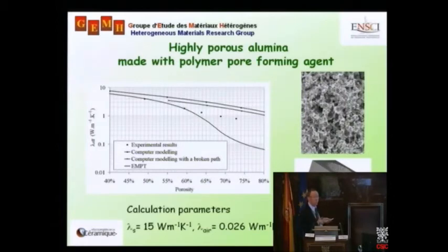But then if you think about it, it actually seems rather reasonable, because obviously when we make ceramics, we like them to have a minimum of mechanical strength. So this means that if we want some mechanical strength, we have to have a continuous solid network. And Landauer's model is based on random grain positions. So at the percolation threshold, we would start cutting up this solid skeleton. And we don't make materials like this.